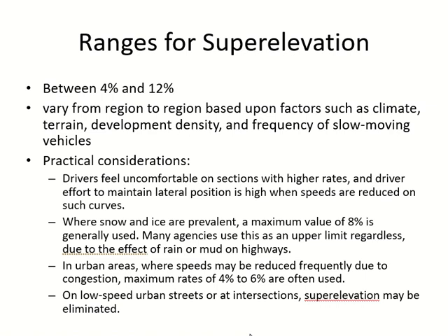Sometimes the curve is very big, or the speed is very slow, or both. I have a very big curve with a very slow speed, then superelevation is not the issue. But the road cross section cannot be level. Even if you don't need it for safety, you need it for drainage, not only for the curve but in all locations. You cannot have a flat cross section because you'll have drainage problems.